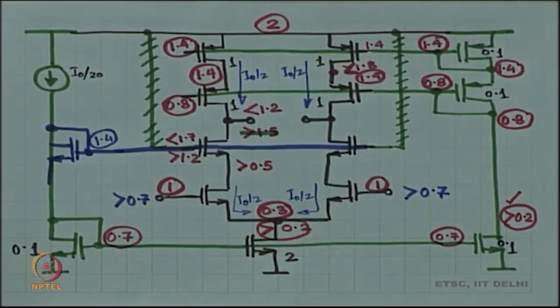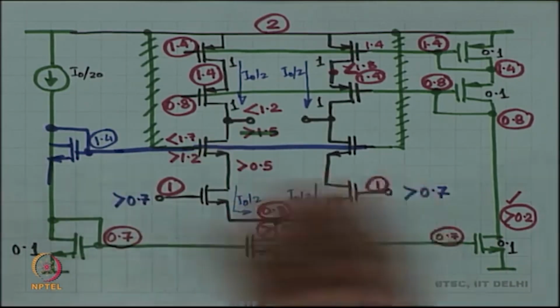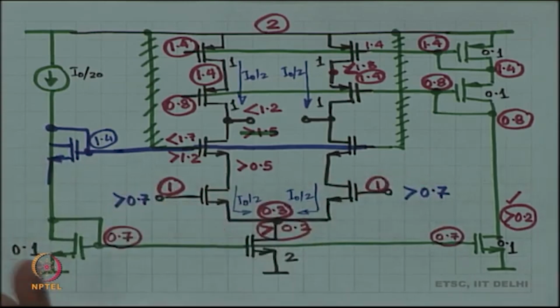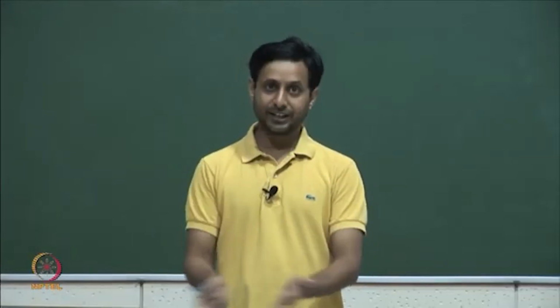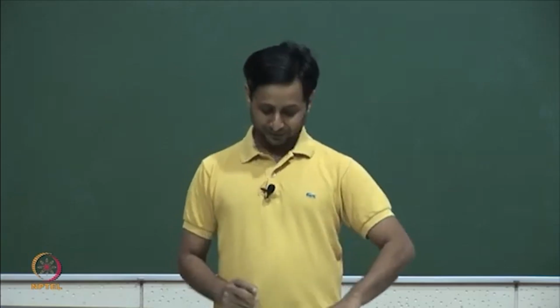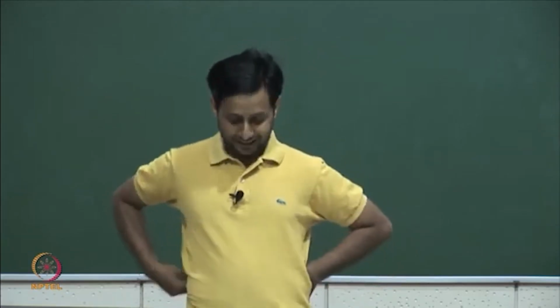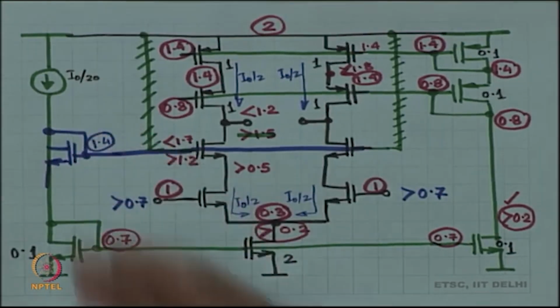Okay. So, you have to do these things a little smartly, it is all on a case by case basis, and you have to be a little creative about it, right. You have to see what is the VT of the device. So, you have to work out all the swings, all the VTs, the VGS minus VT, see exactly what is required, and accordingly creatively design your circuit. And these are the general guidelines. The general guidelines are that you need some swing, right. A cascode, you can use cascoding to generate other voltages.